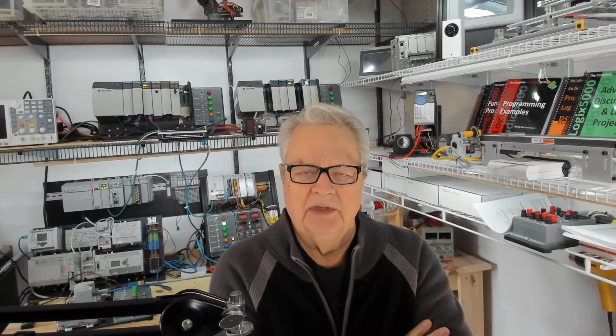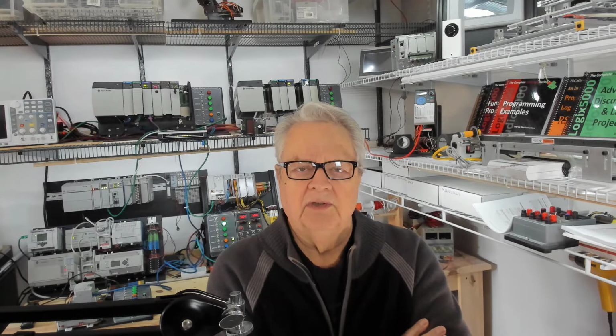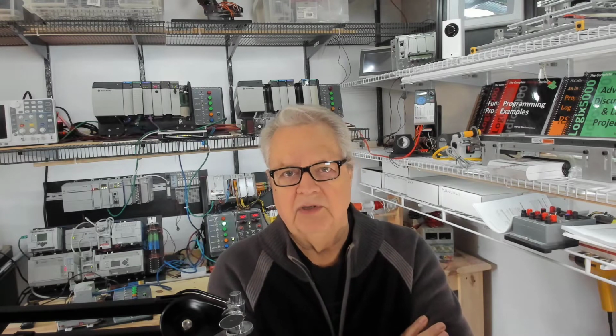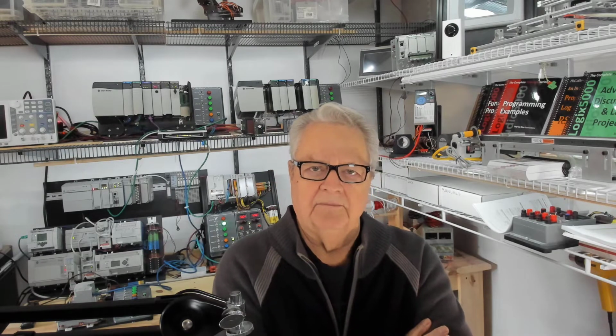What we're going to do in this lab project, and it's part of the same project, is that we're going to reset the steps as we go through the steps. So in other words, step 0 is complete, now we can do step 1. And when step 1 is complete, we set that bit, but we reset step 0 complete.